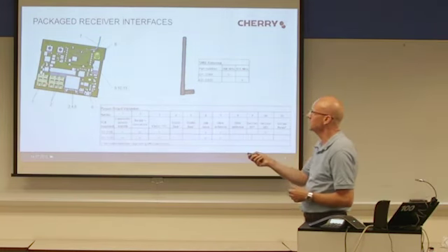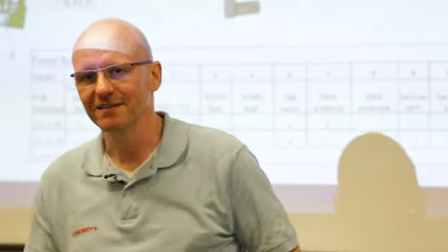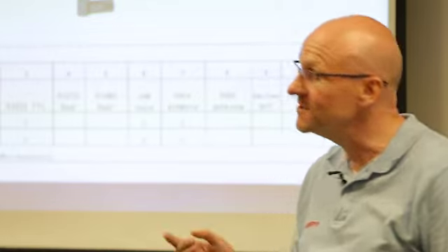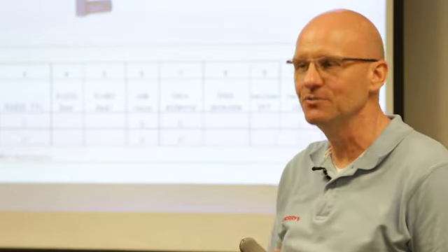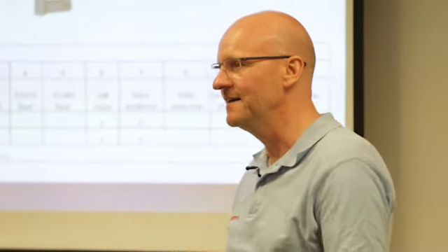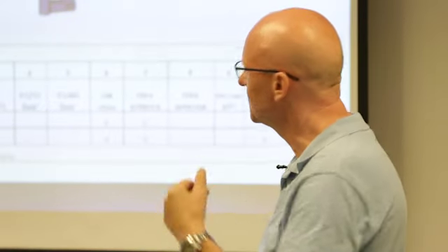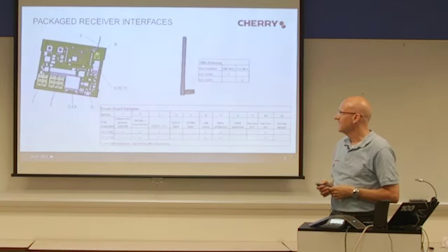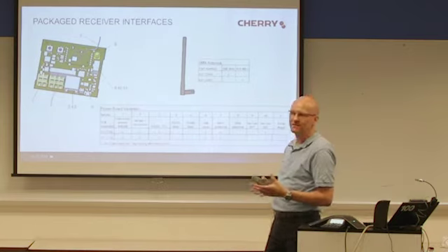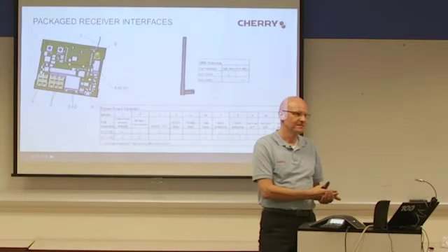And then my host can say, okay, when I get a switch signal or a press signal from sender 17, I switch the light on in the living room. And this is the reason why we need a unique ID, to identify every switch in our system. And the data itself is only 1 bit, press or release.